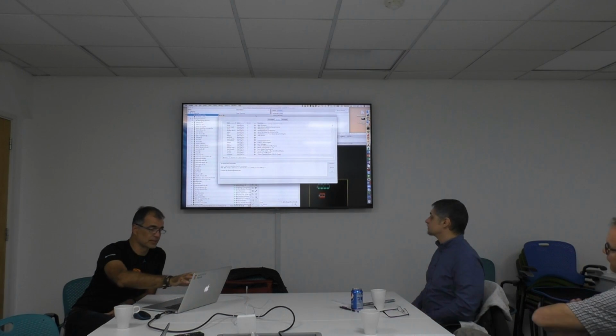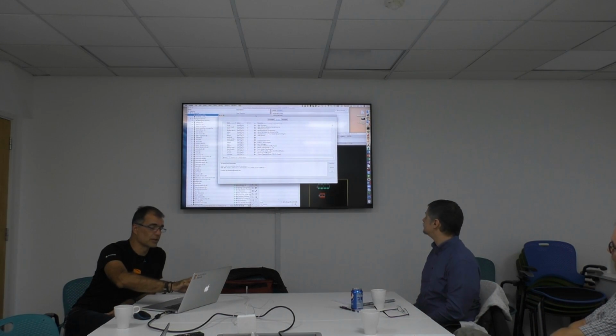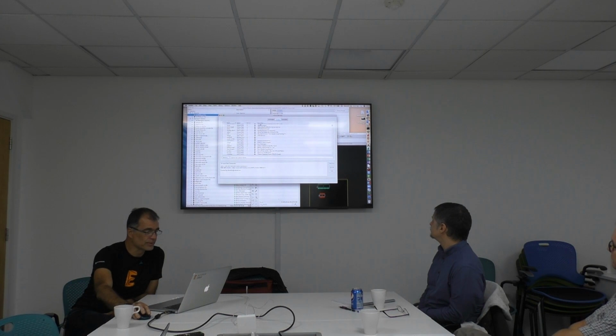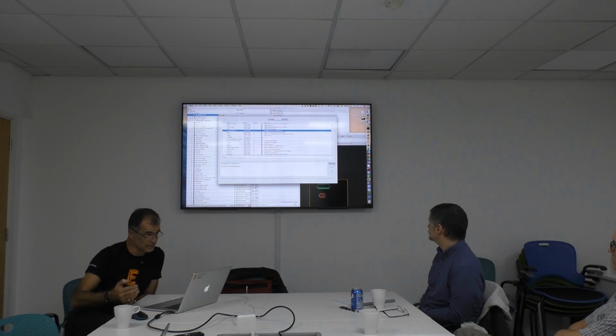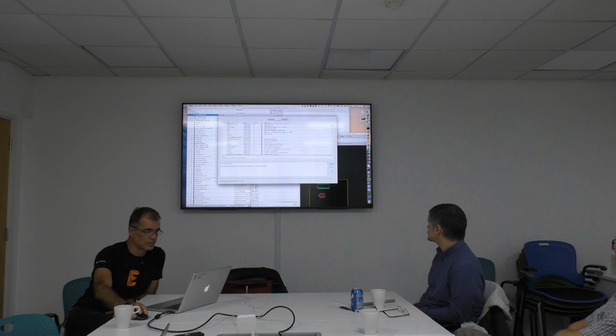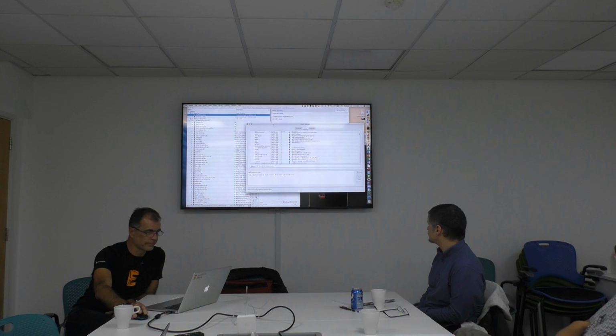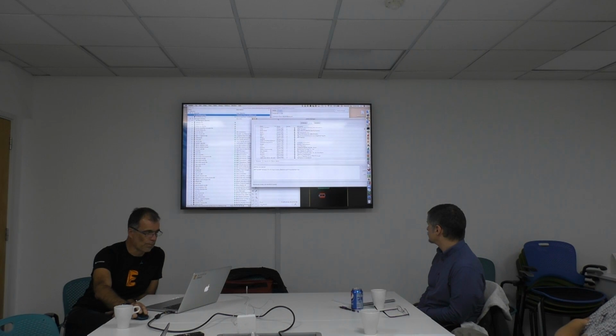I can also take the library manager and click onto one of these and say, okay, this Analog Devices library I do not want to use. I can remove it from the list. It's not deleted, it's removed from the list. If I do so, it's gone here, and it went from green to black. Yeah, here it is.